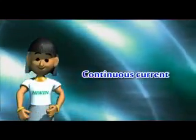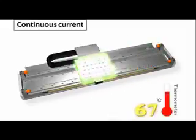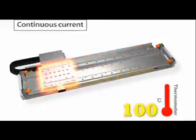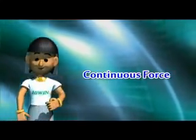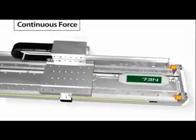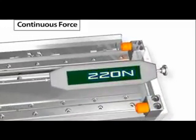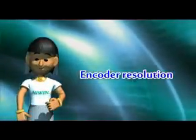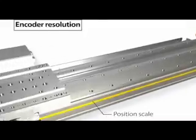Continuous current. A continuous current is defined as a current that can be continuously supplied to the motor coils. This current typically does not cause the temperature to exceed 100 degrees Celsius as it flows through the coils. Continuous force. Continuous force is defined as the force produced by the motor when a continuous current with a 100% load ratio is applied to the motor coils. Encoder resolution. Encoder resolution is defined as the smallest distance that can be measured by the position feedback system.